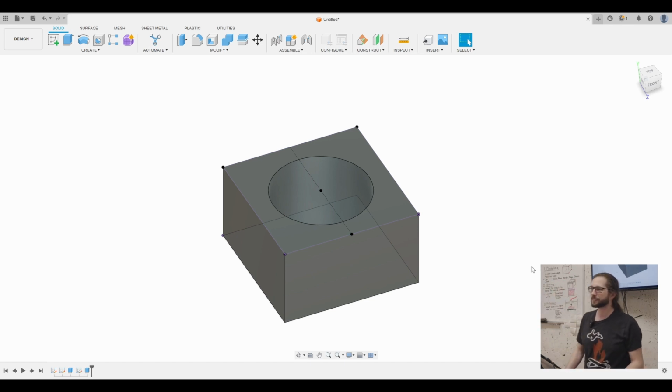Yeah. So you work it so the complexity's at the end of the process, and you have a plan by then. Exactly. You're not trying to deal with the shape or the overall structure when you're working on the details. And you can do that in Fusion too, because as you start adding things, it'll get more and more complicated. And again, that's when you start turning off sketches or bodies that you don't need, so it doesn't have to worry about it.